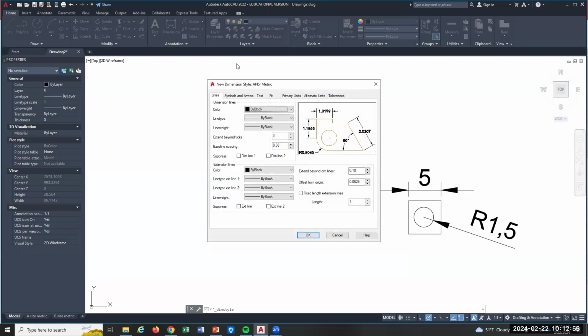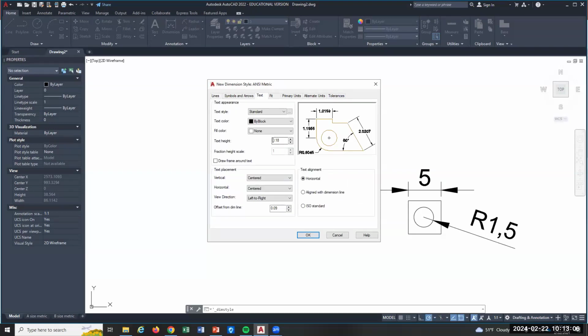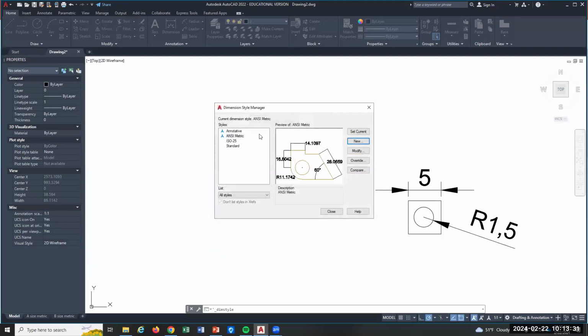And this is that new style. Now, because you're in metric, it pulled in all the dimensions from the US. This is interesting. But in the text, it says, oh, it's like 0.18. That's 0.18 millimeters because it is metric. It's thinking millimeters, which is just microscopic, right? So you still need to put in the metric version of 1/8 of an inch, which would be like 3 millimeters. And unfortunately, there's other kinds of settings that are just fractional millimeters. They're tiny. In other words, if I say okay, and I'm going to set it current, my new dimension style,